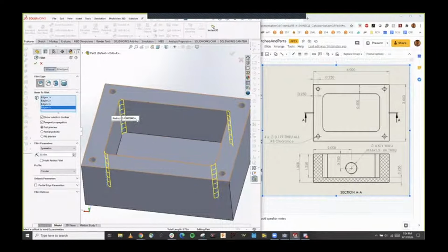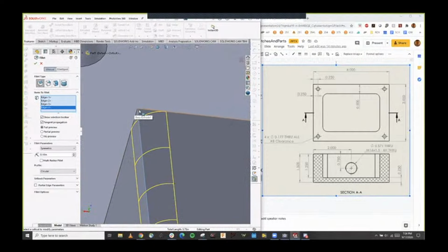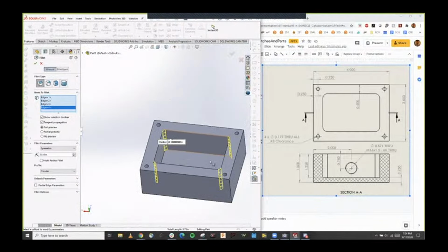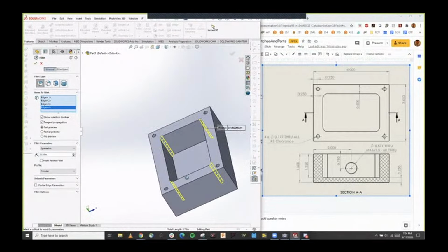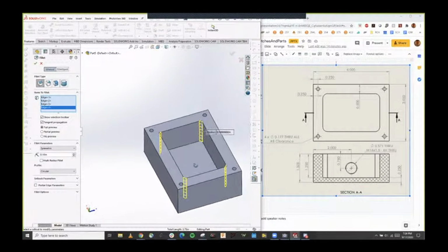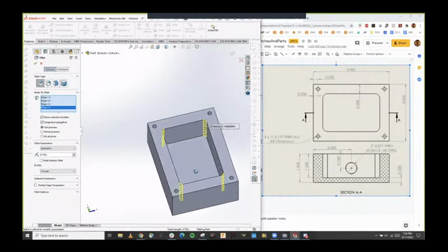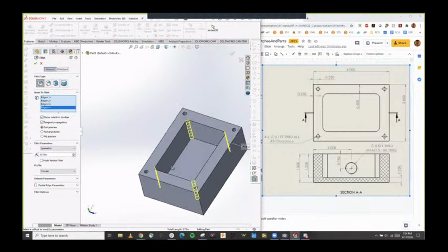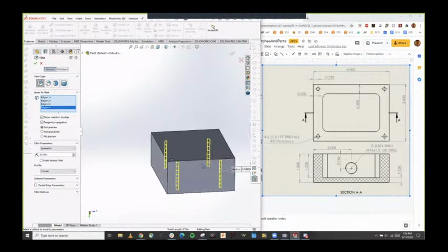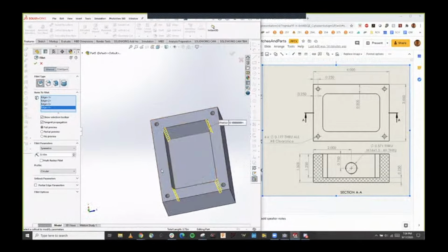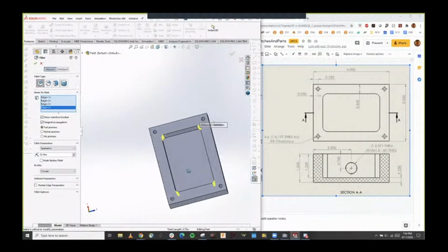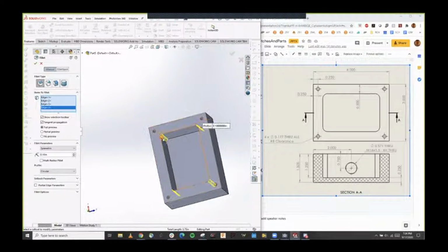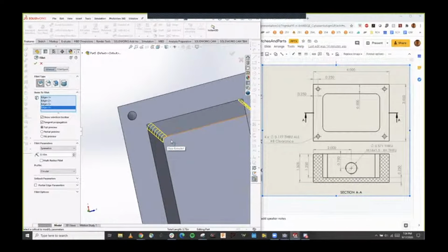The second reason, or I guess this is the third reason we use fillets, is because corners are stress concentrations. So when you create a part, if you need it to hold up to pressure or something, so let's say if this was a lid, this part looks remarkably similar to a lid that was just 3D printed for our ROV robot. So if this has to undergo several bar worth of pressure to survive at the bottom of the ocean or something, then the places where stress concentrates on this are at these corners. Because they're sharp corners, they are where the stress concentrates, and so that's where the part is most likely to fail first.